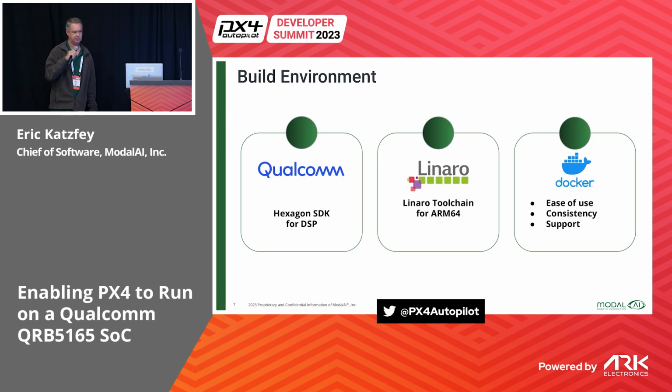Okay, so obviously you have to build all this software. It's a little bit different for this particular device. On the applications processor, if you look at the POSIX platform, that's an ARM environment, and so there is ARM setup. But I think there's a to-do item to go back and look at that whole toolchain for 64-bit ARM. Right now, based on history, we've been using a Linaro compiler toolchain, and we've continued to use that.